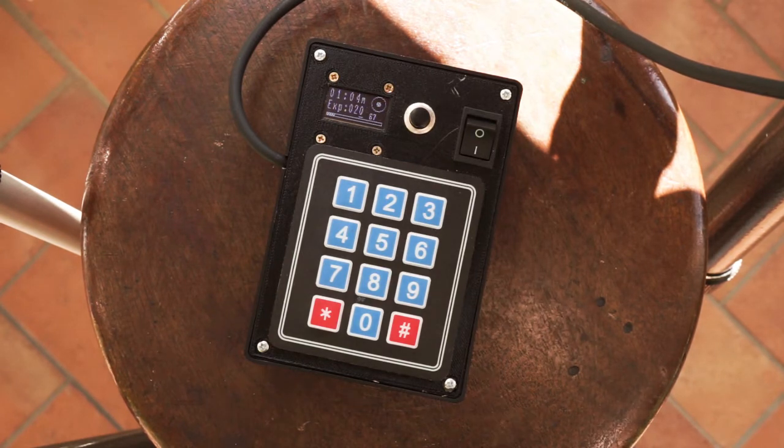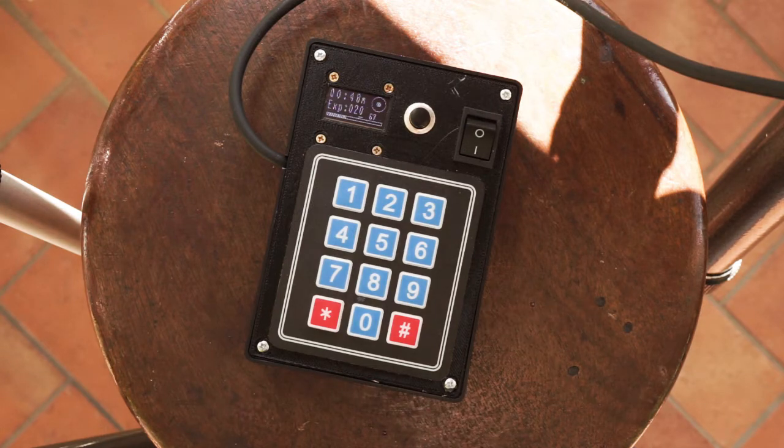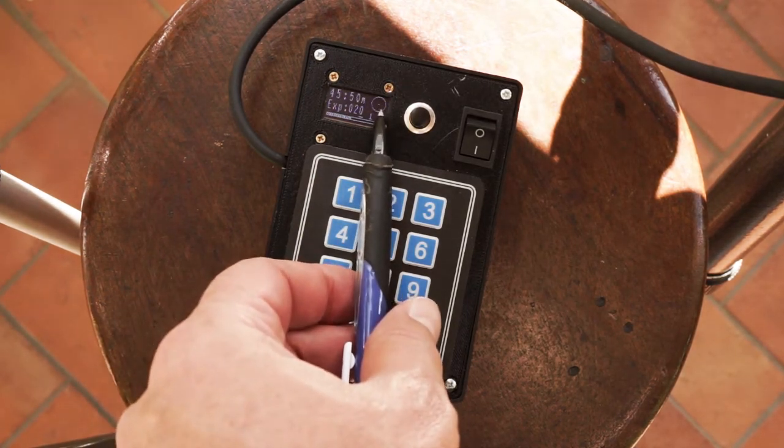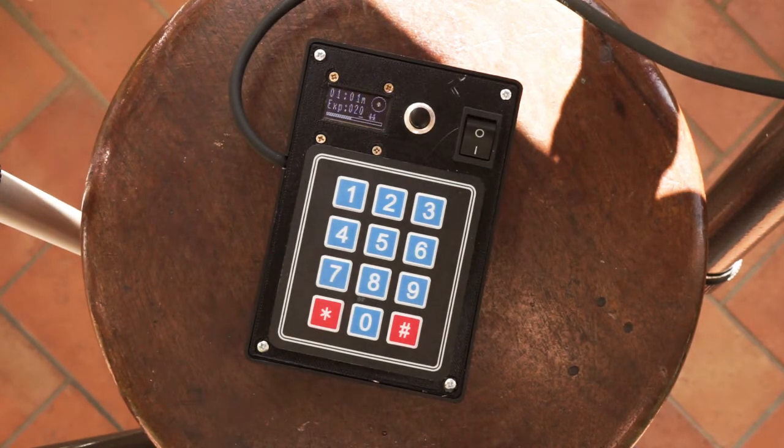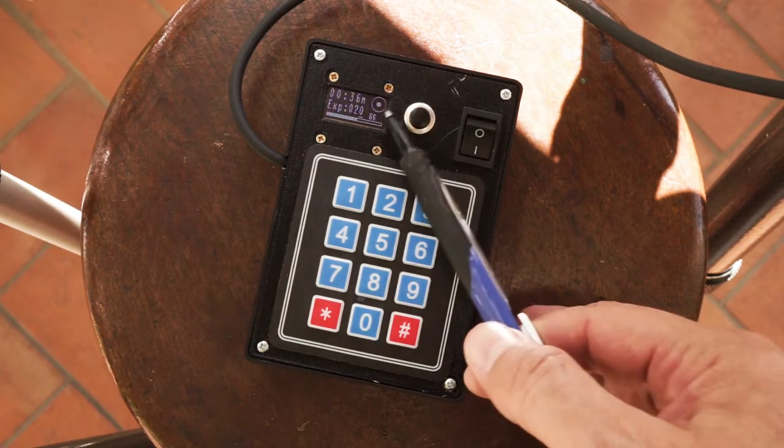From this moment on, when you press the pound sign, the device starts to add up every 5 seconds or so the amount of UV that was collected by your print. And if something happens and the UV level for whatever reason drops, like I'm going now to cover the sensor with my hand, you see that the UV level dropped and the time exploded. Now it's 68 minutes. If I uncover it, it will quickly resume and come back to the level. Now I have again the level 66.